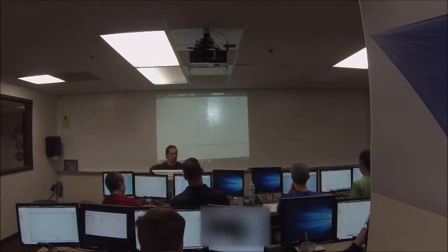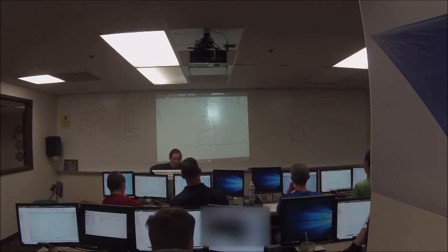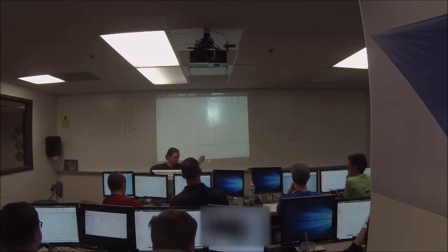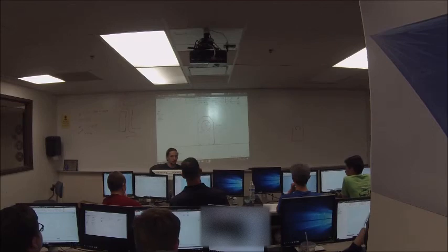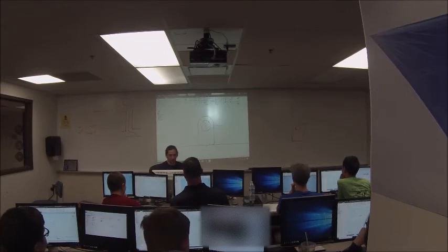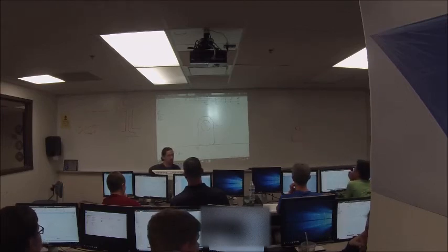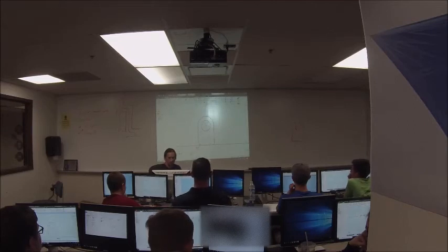But if I change half an inch to 3/4 of an inch, D9 is going to become 3/4 of an inch. So what I want to do is I want half of D9. That's the dimension I want. So I can take D9 divided by 2, press enter, right? Nothing changes, right? Because it was already half the size. But if I go over here and I change this dimension to 0.75, this dimension over here will change as well.